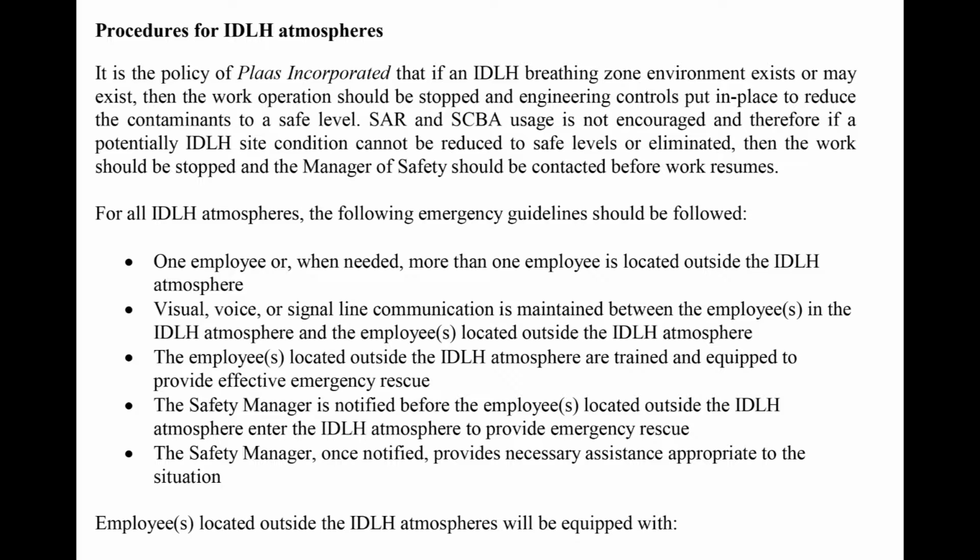The safety manager is notified before the employee located outside the IDLH atmosphere enters the IDLH atmosphere to provide emergency rescue. The safety manager, once notified, provides necessary assistance appropriate to the situation.